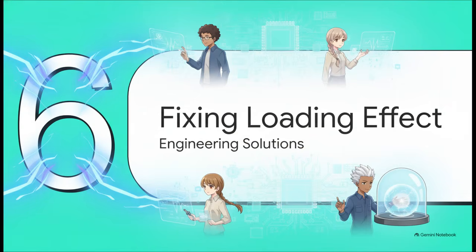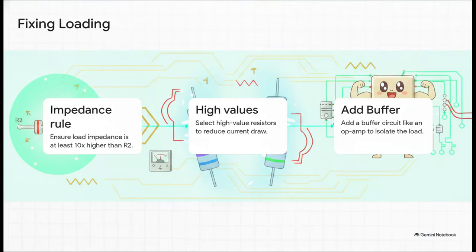But there's good news. Section 6, fixing the loading effect. Fortunately, we don't just have to sit back and accept this performance loss. Engineers have come up with some highly practical solutions to mitigate this inescapable rule of physics. The simplest rule of thumb, make sure your load impedance is at least 10 times higher than the divider resistor it's connected across. This 10 times rule really minimizes that parallel math distortion we just talked about. You can also select high-value resistors to minimize power loss and reduce current draw. Though, a quick aside, be careful with that because it can make the circuit a bit sensitive to noise.